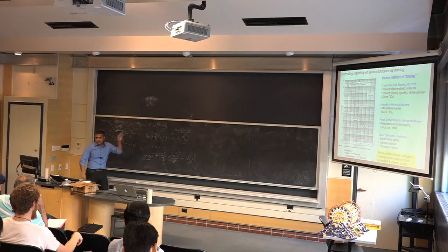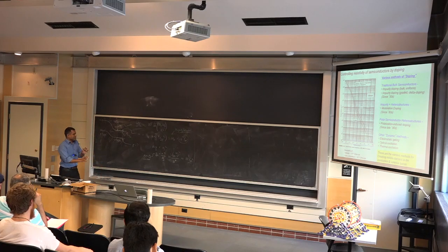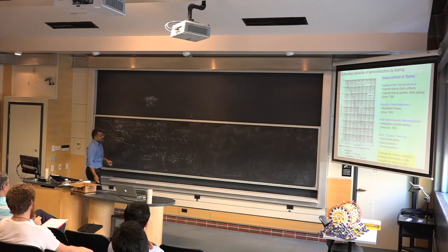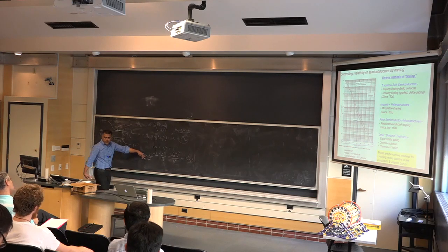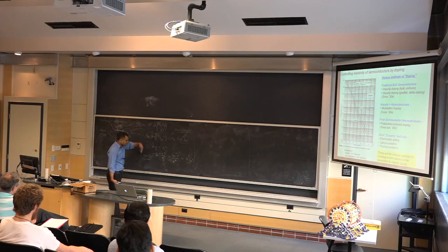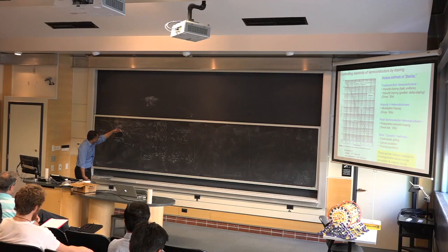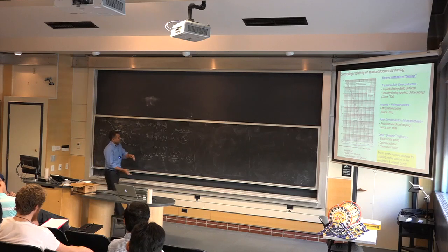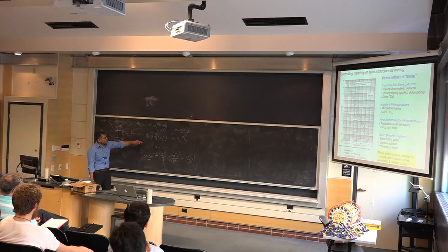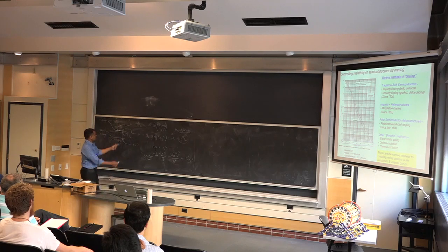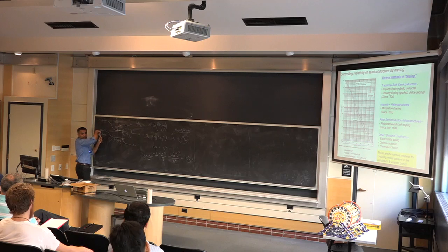Makes sense? This is the way that these names are attached to it. And the reason why you have the minority carriers is again because of heat. Otherwise, there's no reason for it to exist. If you take the temperature away, you will get some. If you degenerately dope it, you can get rid of the holes, but if you dope it heavy enough, you won't be able to get rid of the electrons, for example. Right? So anyway, that's the difference, and you can see that the roles of majority and minority carriers switch as you go here. Here you have many more holes, but very few electrons. Right? So, yeah.